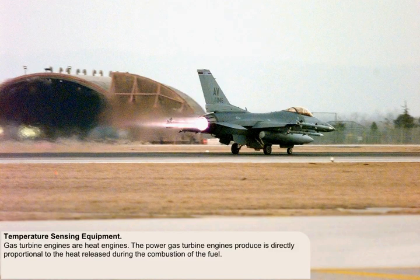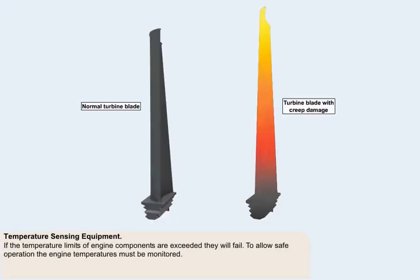Gas turbine engines are heat engines. The power gas turbine engines produce is directly proportional to the heat released during the combustion of the fuel. Engine components and systems are designed to withstand certain temperatures. If their temperature limits are exceeded, they will fail. To allow safe operation, the engine temperatures must be monitored.